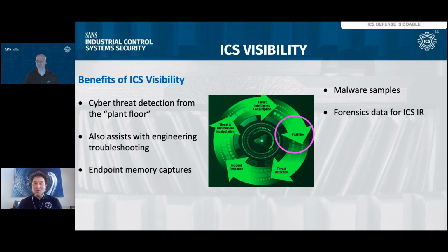I can't tell you how many times we've deployed sensors in a passive way inside substations and refineries, and they say, hey, we've been trying to track and troubleshoot something from an engineering perspective for months, and you guys now have packet captures. Can you help? Absolutely. By the way, we've just seen that your HMI is trying to send something to a meter in the field using a protocol that the endpoint doesn't understand. So that's probably where the issue is. Here's the PCAP. So a lot of value from a security perspective, but a lot of value as well with engineering and helping troubleshoot.